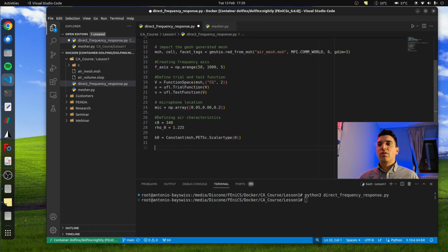First thing, we are going to define the normal velocity boundary condition. So we will assign a random value. Let's say normal velocity, we will assign a value of 0.1. This is meter per second. It's a pretty high value, I know, but it's just a linear problem.